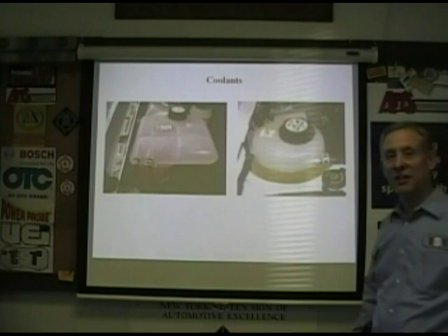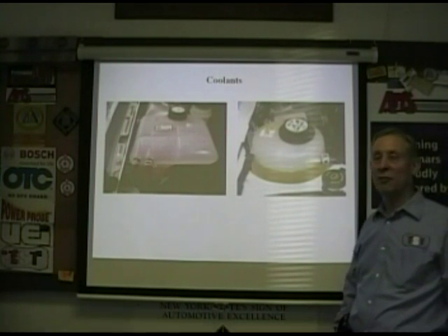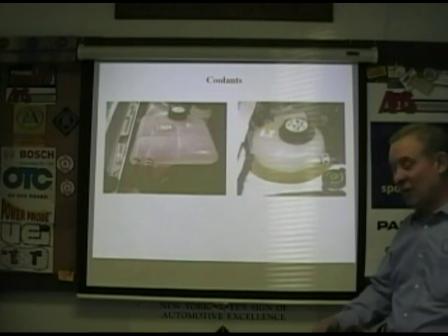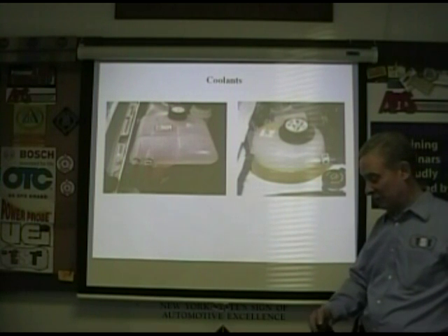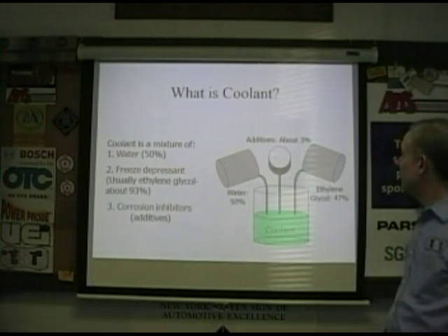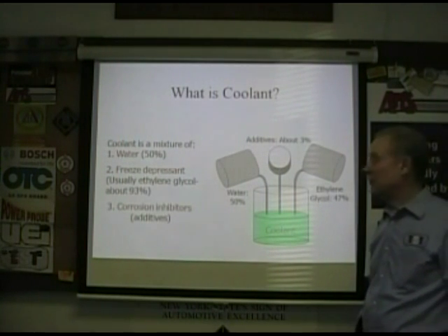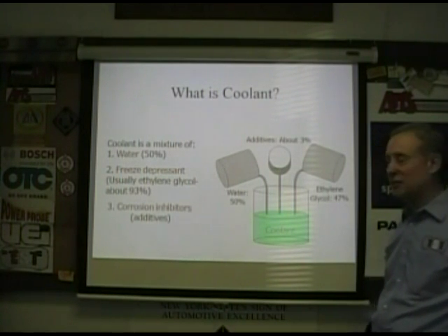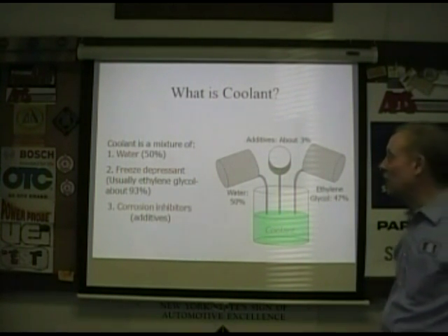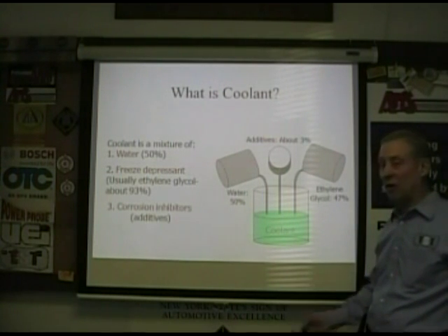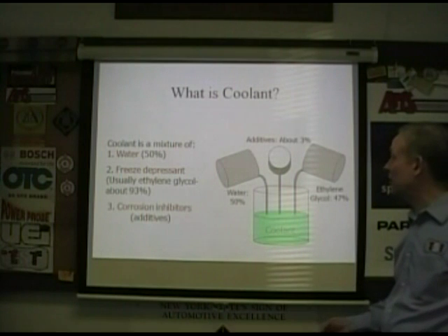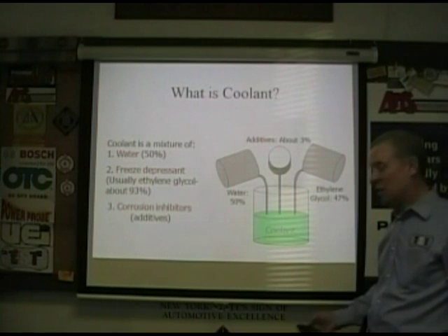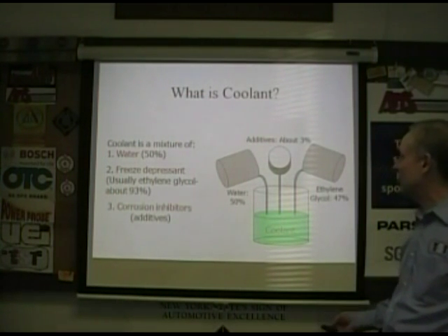Okay, welcome to the TST seminar. What you don't know about fluids, this is the coolant section. We're going to go over the chemistries involved and what you need to know to put the correct coolant in vehicles that you service. All right, what is coolant? We all think we know this. Basically, it's generally a mixture of between 50-50 and 60-40 ethylene glycol and water. There are some propylene glycols, we're going to get into that, but for us it's ethylene glycol and water. There are other additives, lubricants, water pump lubricants, rust inhibitors, and other additives that we're going to go into.